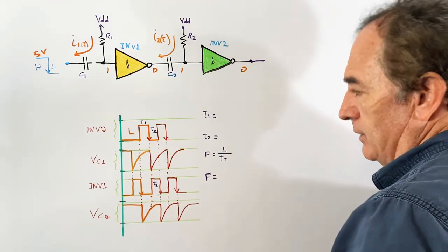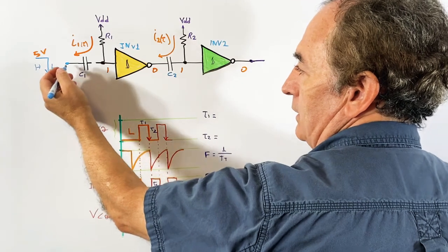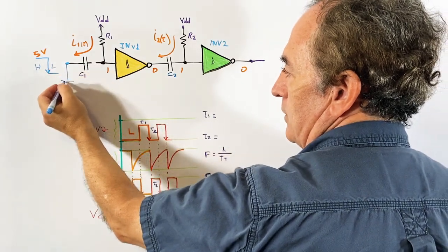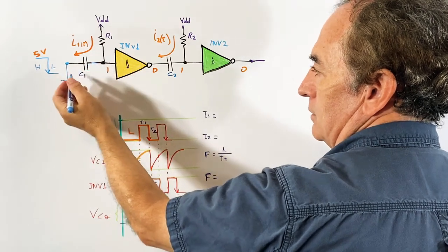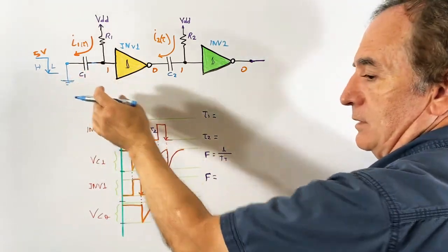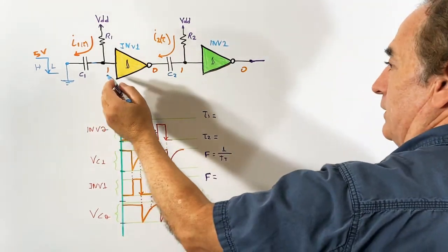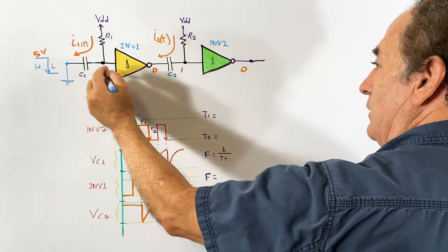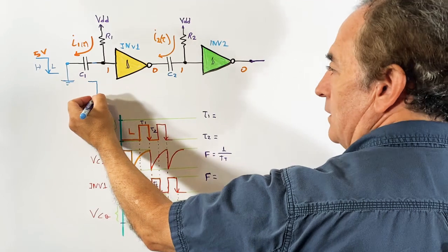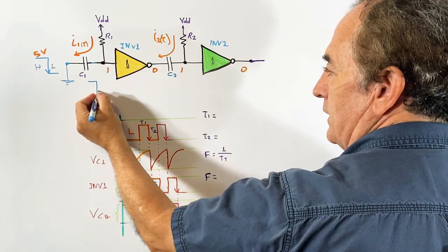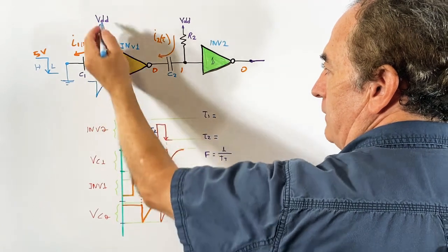Now when you trigger the input at the falling edge, now you have 0 volts right here, and the capacitor gets closed in time t equal to 0. It is a closed circuit. So you have the voltage across the capacitor behaving like this. It goes to 0 volts and then it starts charging, okay, to VDD.